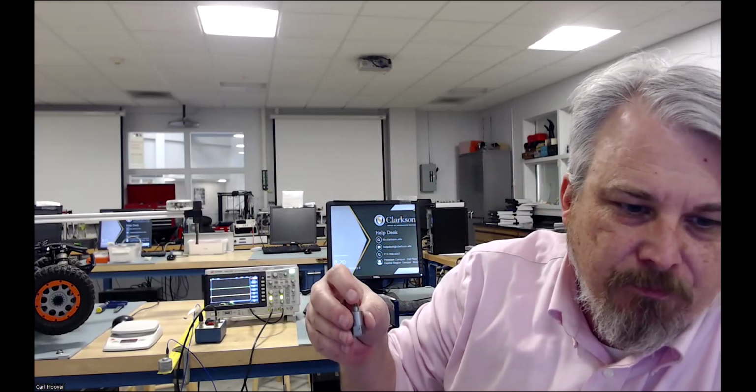Currently I have a little ball of wax I'm just going to use to adhere the accelerometer to a surface as it's moving up and down. We'll measure that. So the beam that we're going to be using is essentially a yardstick clamped to a table, so it's cantilevered with an accelerometer mounted, and then also a stack of added masses or weights here.